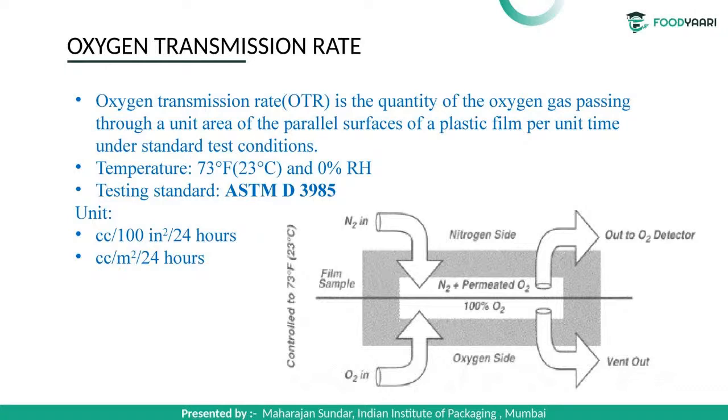Polyvinylidene chloride, PVDC, is 0.05, and acrylonitrile is 1.0. But this EVOH has a good oxygen barrier, but it doesn't have a good water barrier. Likewise, PVDC generally has the best oxygen barrier and water vapor barrier. It is used as a barrier material universally.